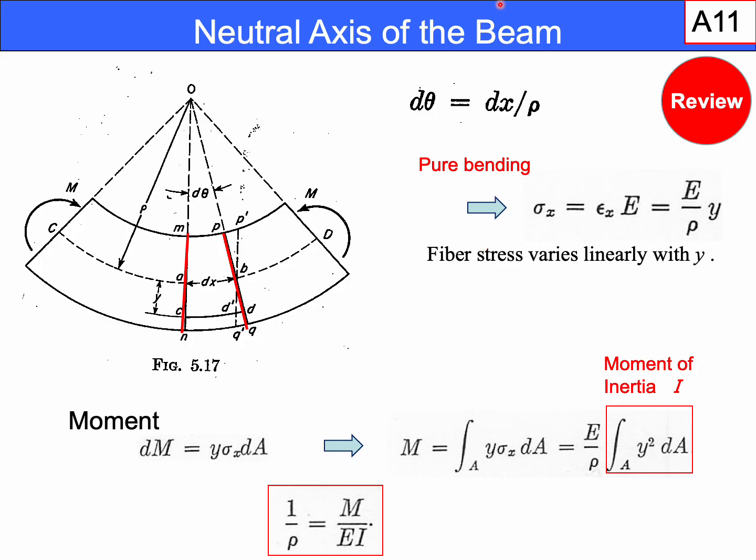The slope of this linear stress distribution depends on two key factors: the applied bending moment, and the second moment of area, also called the moment of inertia, I. This is defined to be I, the moment of inertia. The relationship is fundamental and leads directly to the bending stress formula that you have already studied. Understanding where the neutral axis is located is therefore essential for predicting maximum stress and ensuring safe design.